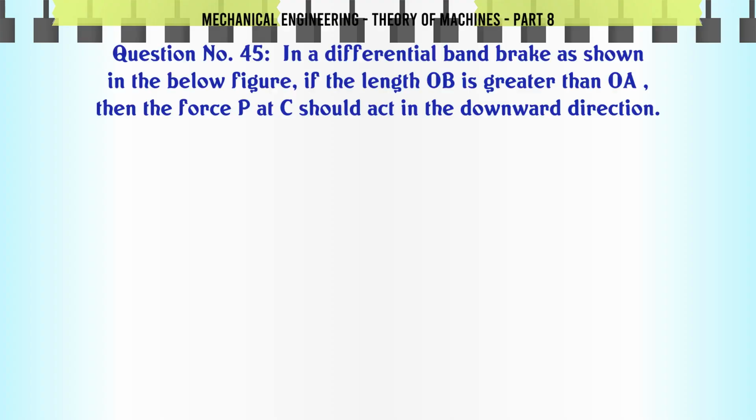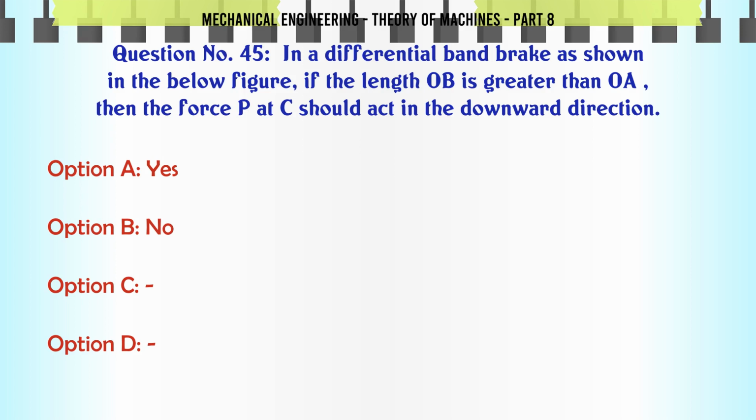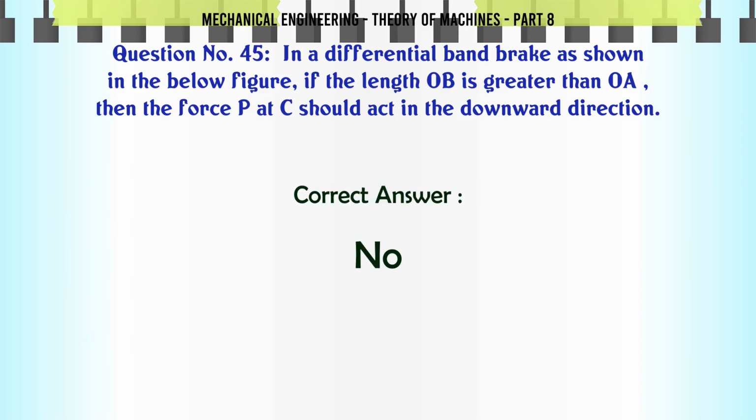In a differential band brake as shown in the below figure, if the length OB is greater than OA, then the force P at C should act in the downward direction. A. Yes, B. No. The correct answer is no.